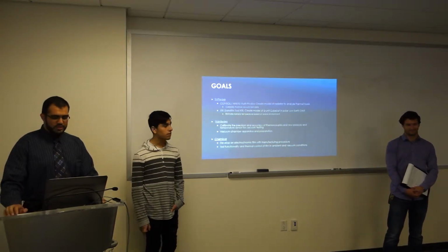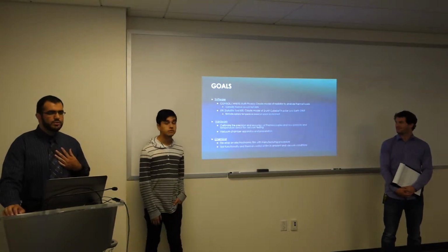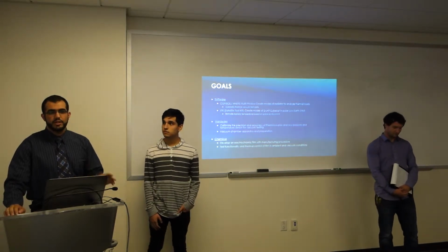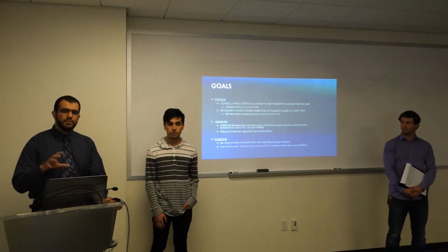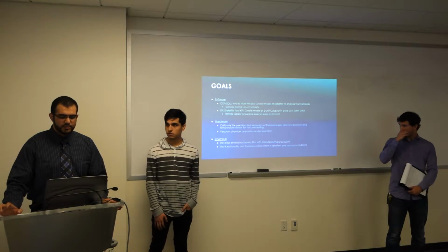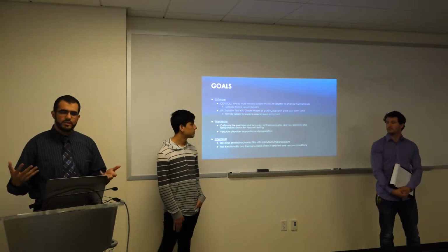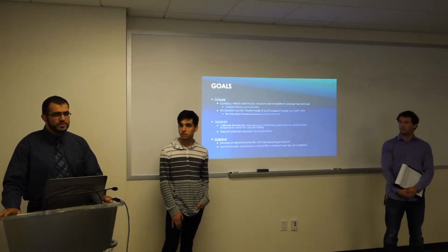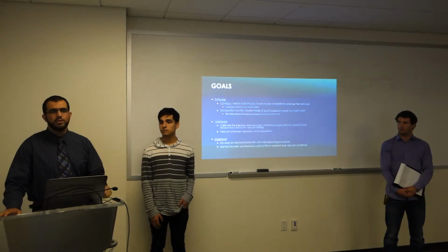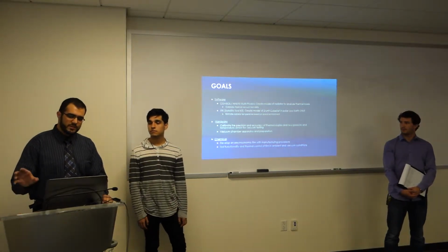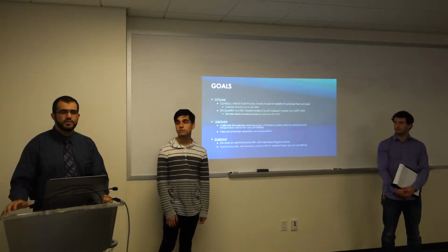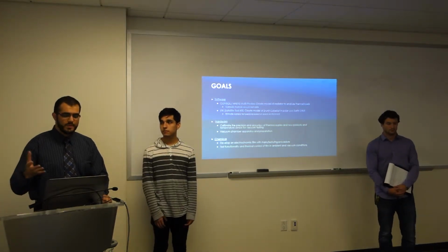So our goals for this project, software-wise, were to use COMSOL or ANSYS Fluent to create a model of the radiator and analyze the thermal loads on that radiator. After that, we would correlate the data we get from the software to the data we obtained from the tests we did at Boeing, and see how our software reflects the actual experiment. We also used Satellite Toolkit, also known as STK, to help model the two-unit CubeSat in polar low Earth orbit. From there, we were able to estimate the radiator temperature on each side of the CubeSat, to give us a feeling of what's going to happen in the space environment.